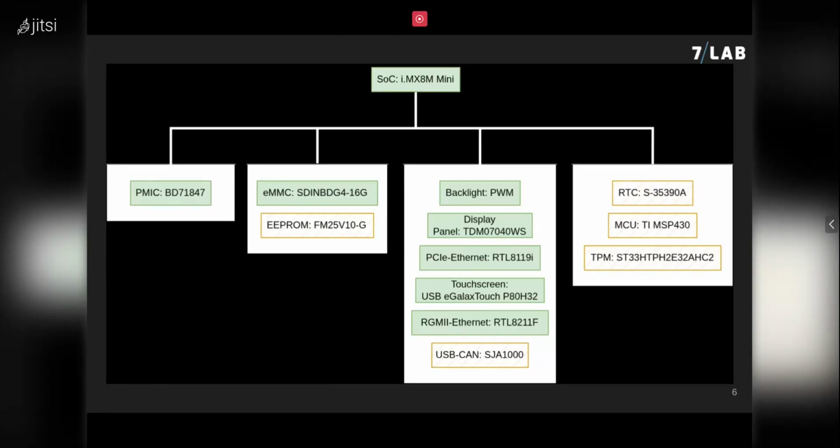And they had an actual TPM, which is usually not needed for Android because that's not how the Android security model works, because they heavily rely on the RPMB area on the eMMC, which I mentioned before, and combine that with secure boot and the Trusty secure execution environment.